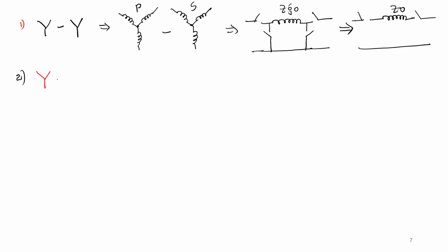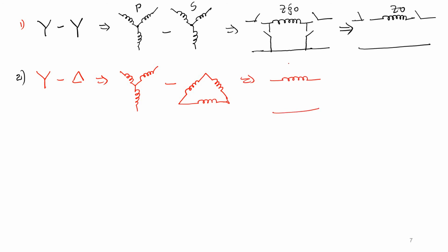The second connection is star and delta. Let us draw with respect to the reactances: this is the star connection and the delta representation. Take the generalized zero sequence network with series switches and two shunt switches. What is the resultant network? It is a star connection but ungrounded, so the series switch will be open, and here it is ZG0.